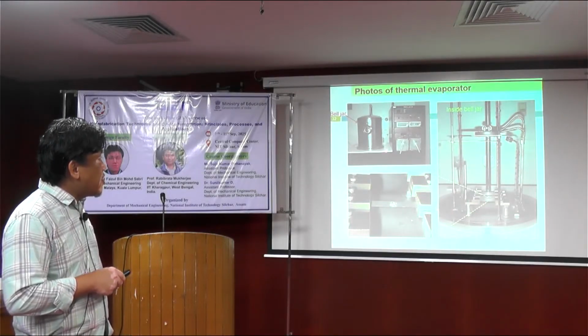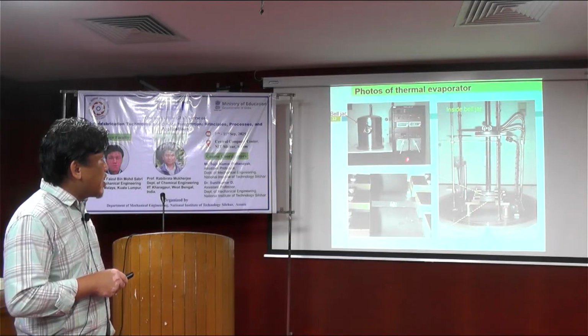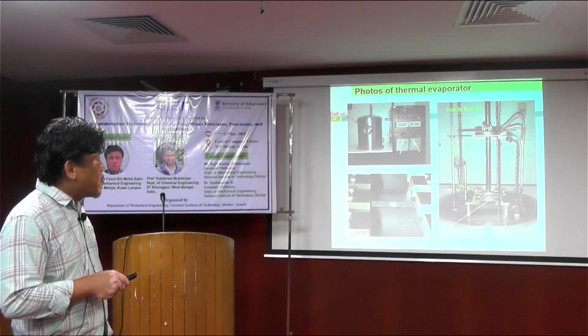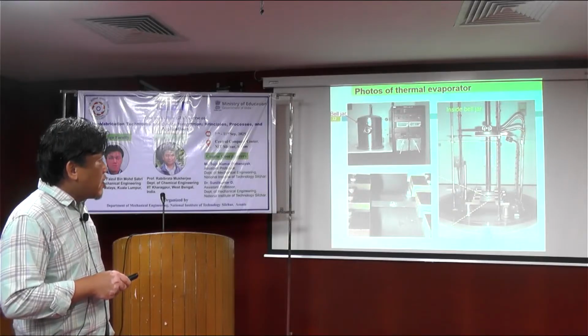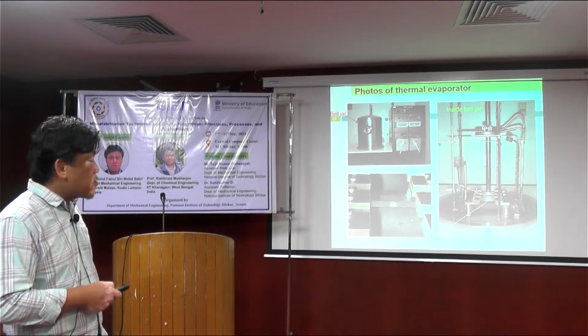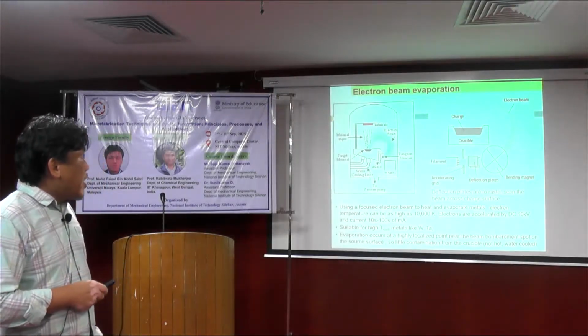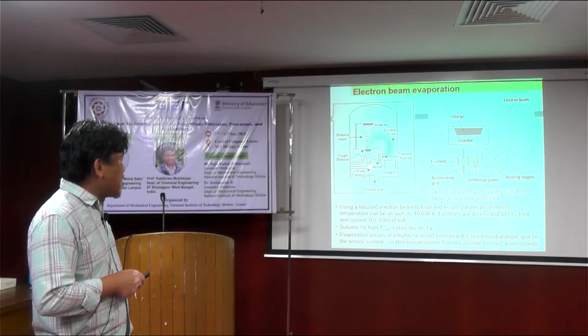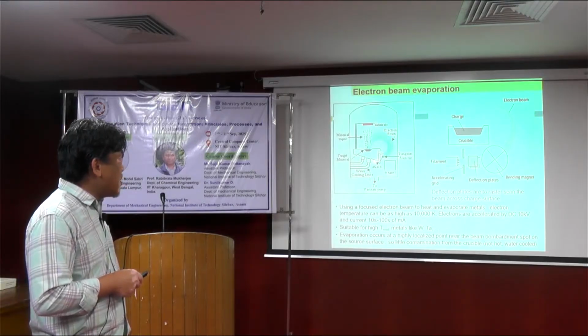When you vacuum the jar and heat up the materials here, you put your wafer here, then you can deposit the materials. And this is for electron beam evaporation. It's just a matter of a different heating method, but the process mechanism is the same.